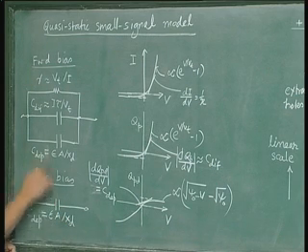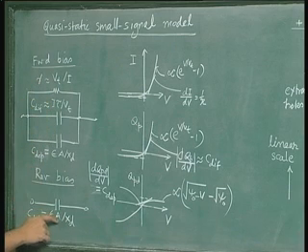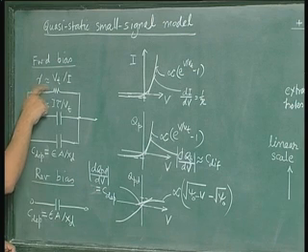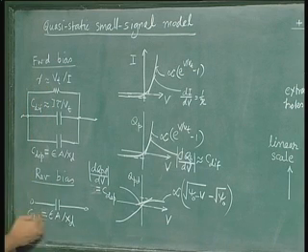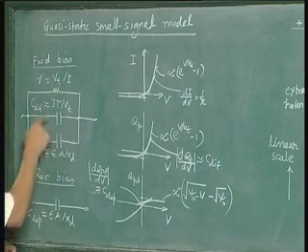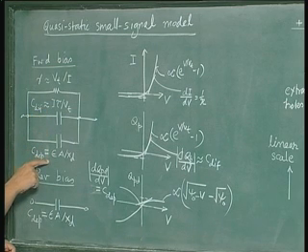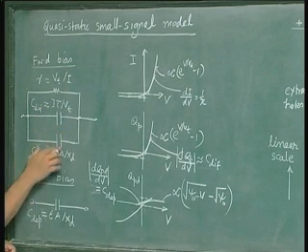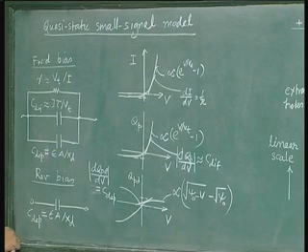We do not show any diffusion capacitance or resistance in reverse bias because, as we have said, diffusion capacitance is negligible and resistance is very, very high. Okay, so those two elements are not existing for reverse bias. For moderate forward bias, where the devices are operated, generally the diffusion capacitance dominates over the depletion capacitance. So this quantity is negligible, okay, for moderate forward biases.